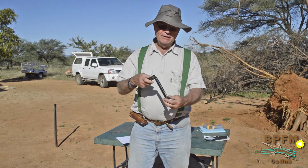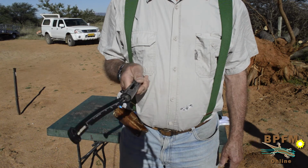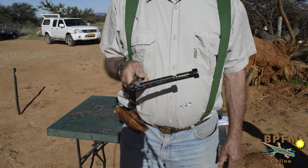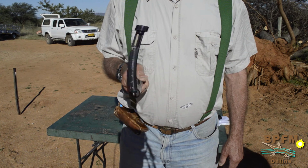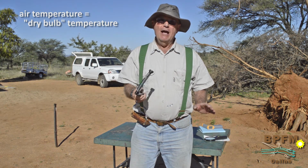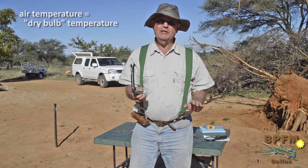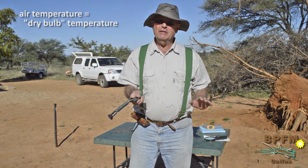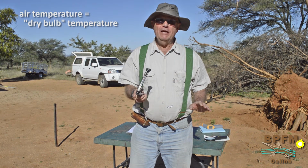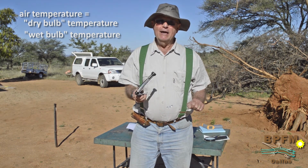Now, if I take this device and I swing it around until both temperatures of the thermometers come to equilibrium, one will show air temperature because it has no sock on it, it's just being ventilated by the air, and it will actually reach something very close to air temperature. And the other is evaporating water until it comes to its maximum evaporation point, and then it'll stop, the temperature will stop going down. That will be the wet bulb temperature. From those 2 temperatures, when I read this, we'll be able to calculate both relative humidity and absolute humidity.